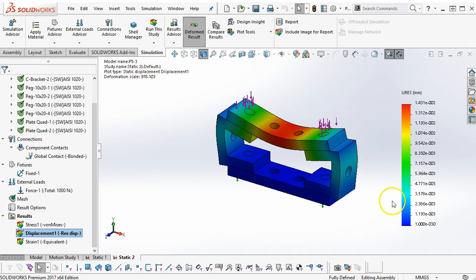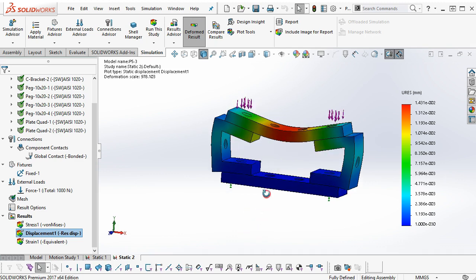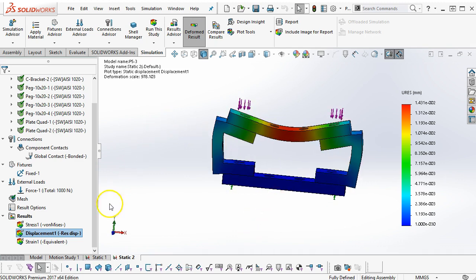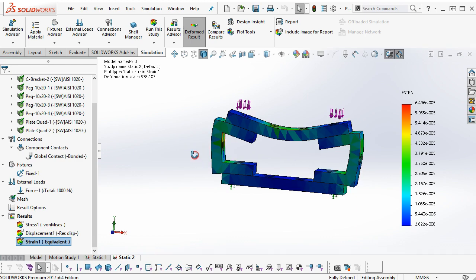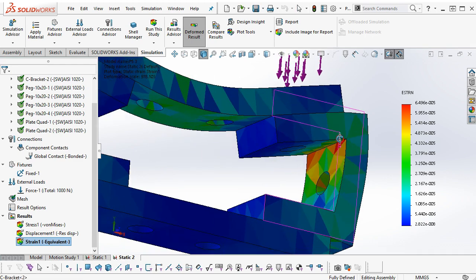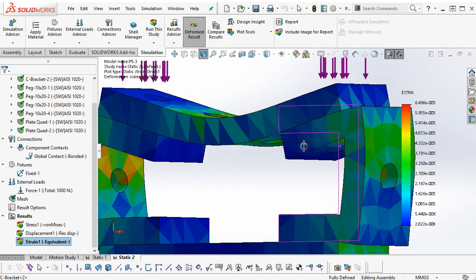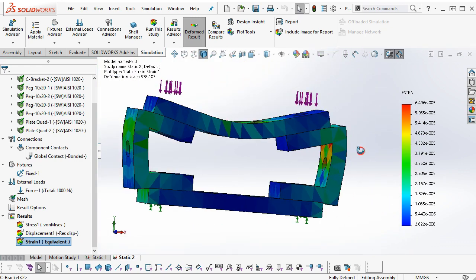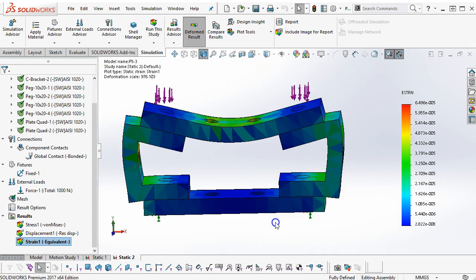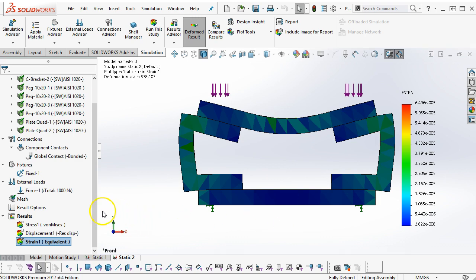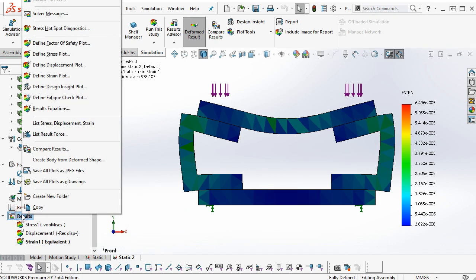So displacement, also at full scale, but then you look at the millimeters. Red is at 1.4 to the -2, so move those over, 0.014. It's a very small amount, even though we're looking at that deformation as being dramatic. And then the strains into the corners, obviously at the stress risers and the internal segments at the top side, give us a pretty clear sense.